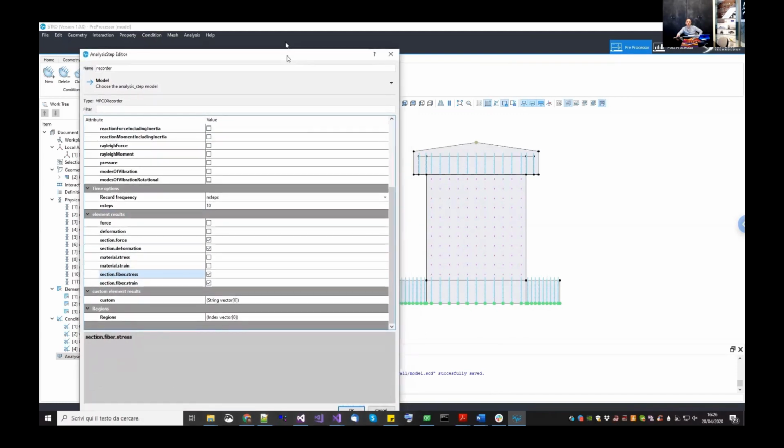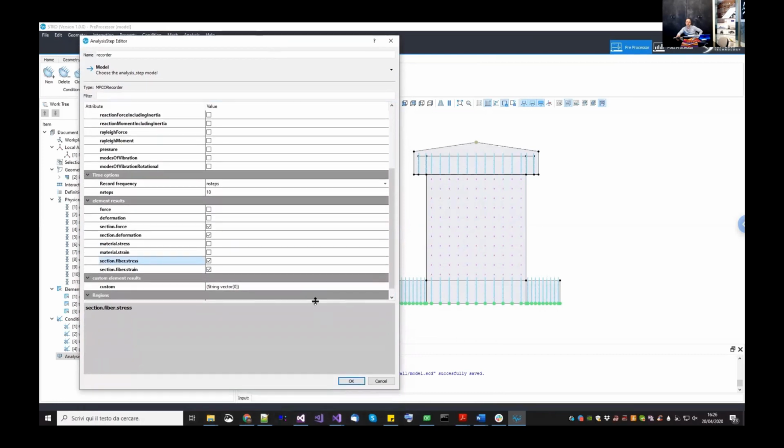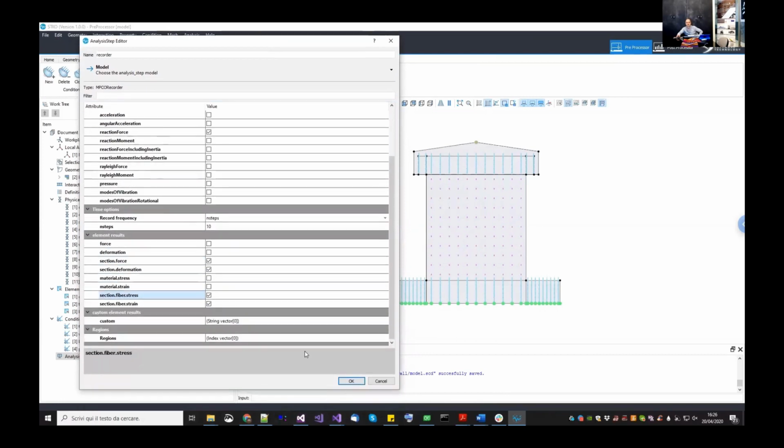Okay, now there is another option, before I didn't use it, but now we have it. This kind of material model that I put in OpenSees has an extra result, which is not common to every material, so that's why you cannot find it here. But in this model, you can ask for the damage variables, so positive and negative damage, and for the equivalent plastic strains, positive direction, negative direction. But how do you do if they are not the common ones that are here?